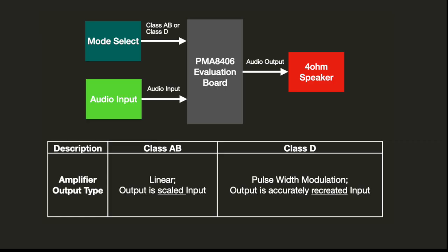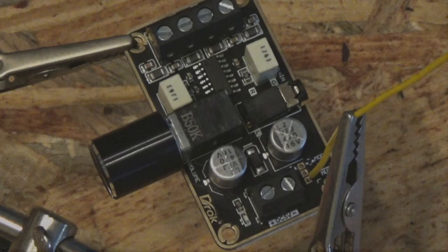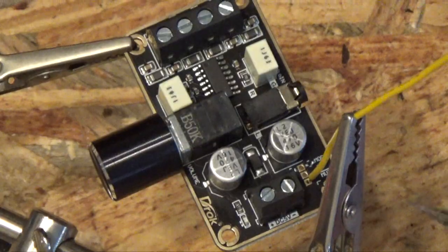When I first got this board, I was a bit disappointed because the mode was not actually working. Upon further investigation, I realized that the mode was selected by the factory because it had a 0 ohm populated resistor that tied it to a power supply. In order to figure this out, I first had to populate wires so then I can interface with the board.